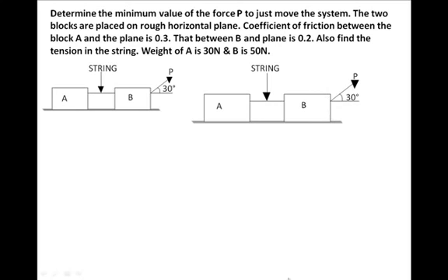So with this background, let's draw the free body of both the bodies: the weights, the reactions, the tensions, and the frictional forces. Now, the values of mu given in the problem are different, they are not the same. One is 0.2, one is 0.3, but that's okay. That will be reflected when we substitute. So after drawing the free body, for each body you write the static equations of equilibrium, that is sigma Fx = 0 and sigma Fy = 0.